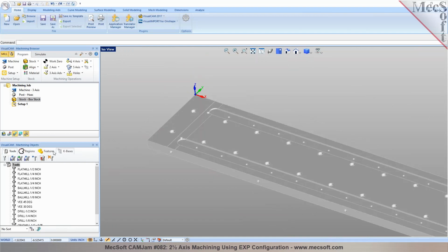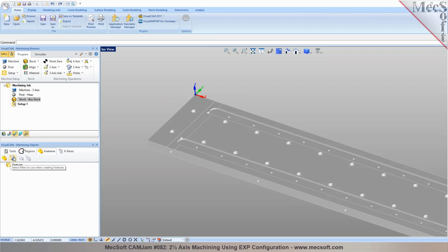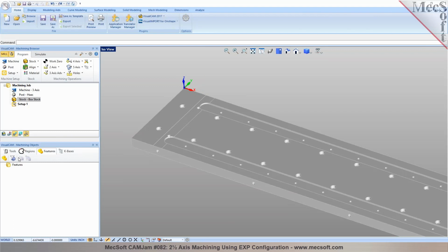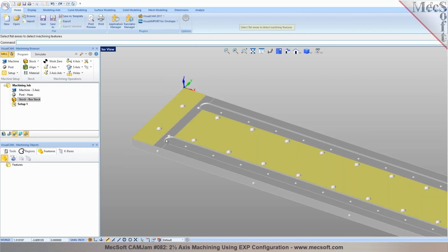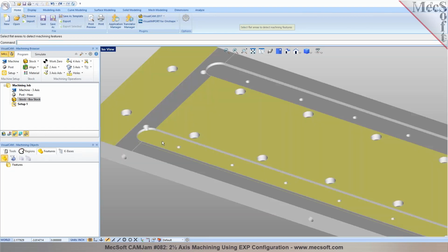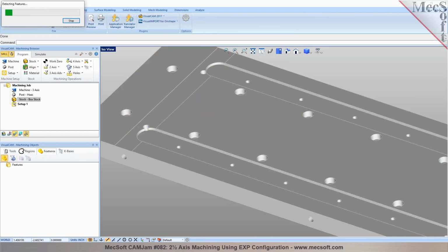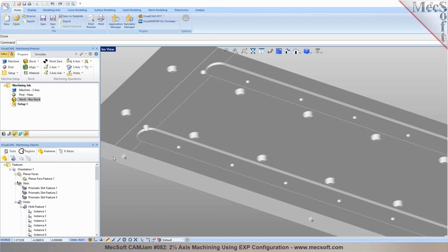All right, I could show you how to program it in here. So, we have a feature called Feature Detection and Machining in our 2017 version, and this is offered right from our standard configuration. So we can use those for identifying the features from the part. For example, I can select Create Machining Features, and I can go pick this face and the part right here, and this will automatically identify features on the part right in here. As I select them, I can right-click on it, and this will automatically go through the process of analyzing the part, and also it will detect the features on the part.